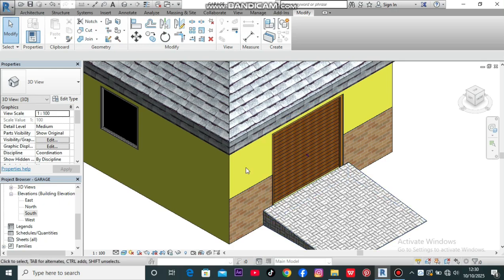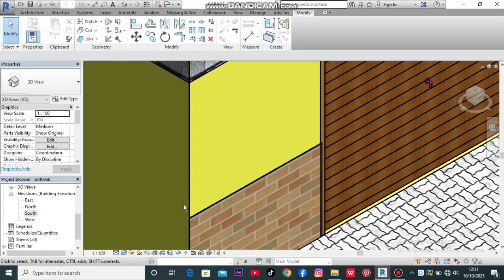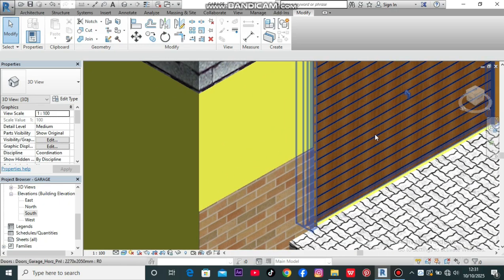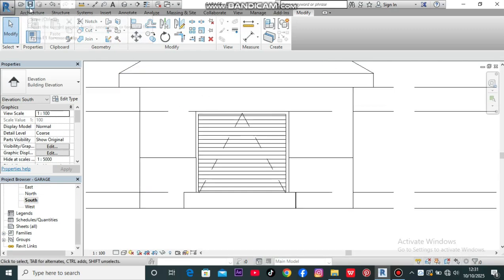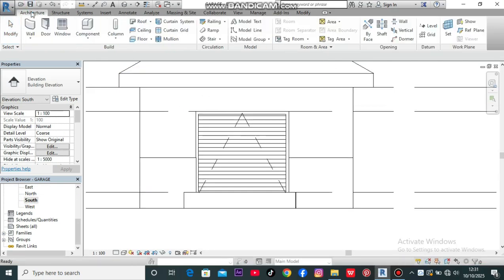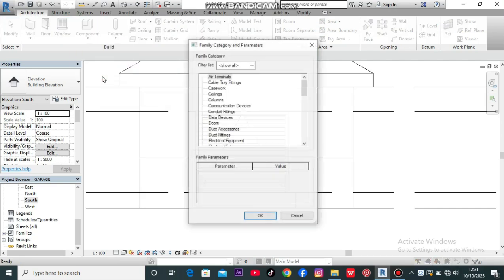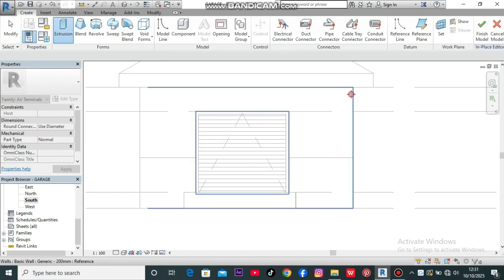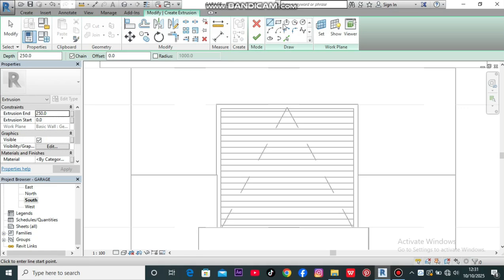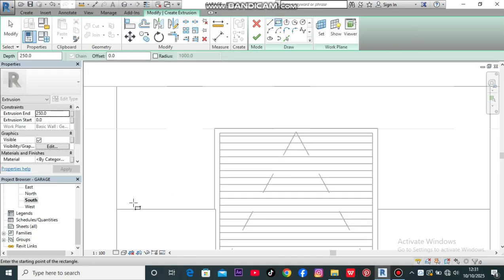Still not looking professional. We need a white model here again. Edit in place again. The split has to get something that's going to split it, so make sure you select that wall again. All right, we have the view. Then choose rectangle from here.